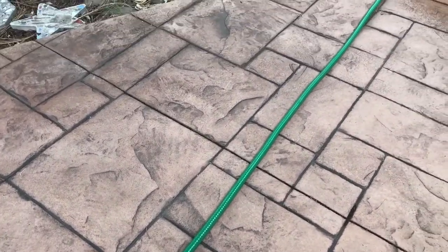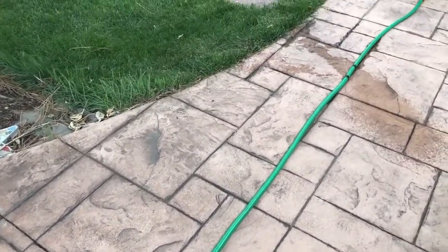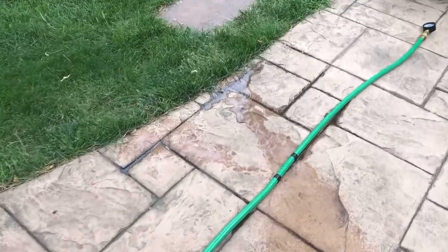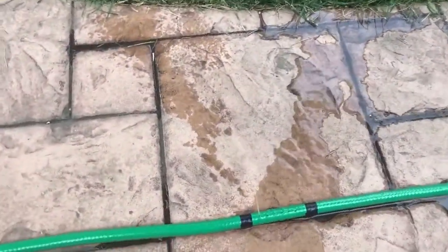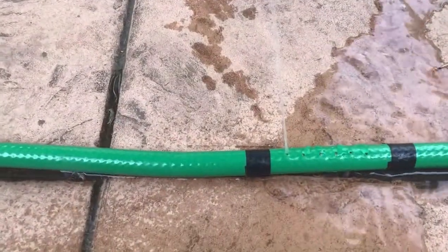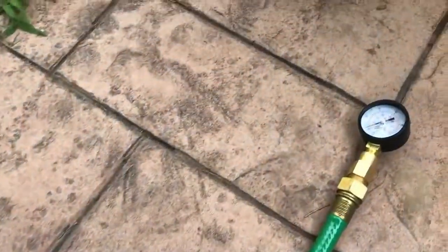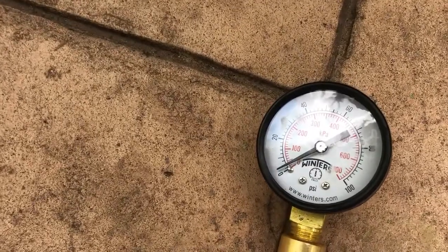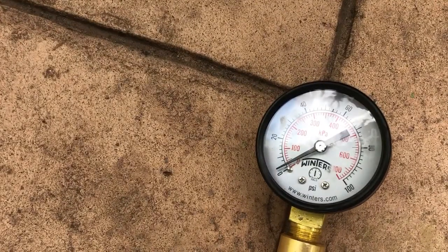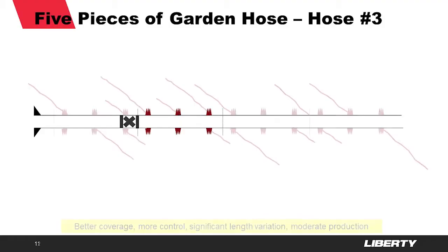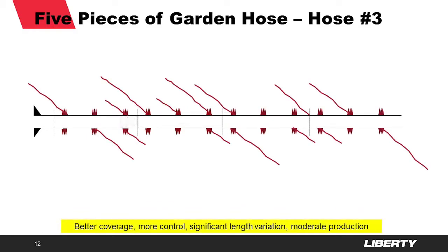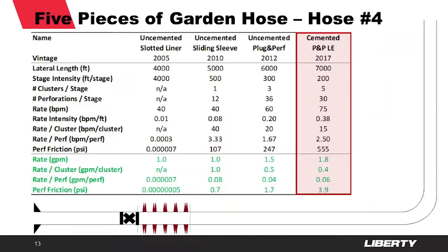Pumping slickwater at high rate is not the best design for the service company's equipment. It also took more time to complete and required more equipment. As a result, strategy number 3 was also somewhat more expensive than strategy number 2. The production improvement, however, significantly exceeded the cost increase, therefore minimizing the cost to lift the produced barrel of oil to the surface. Some operators further extended this approach with a higher rate and smaller stage length.